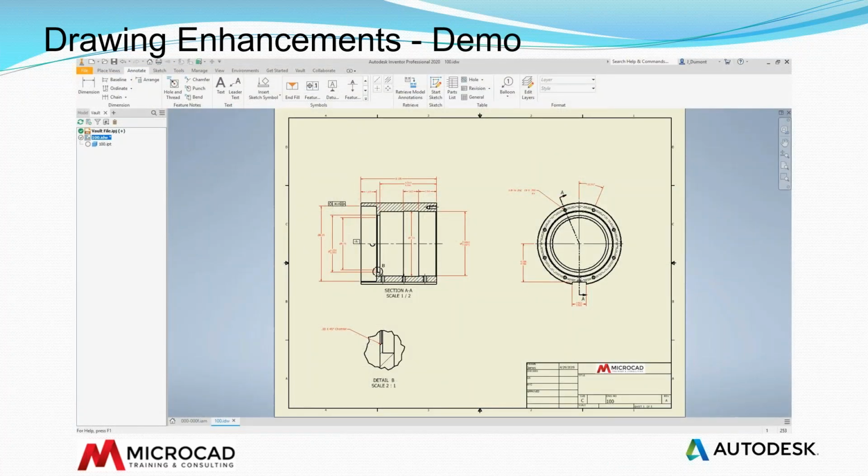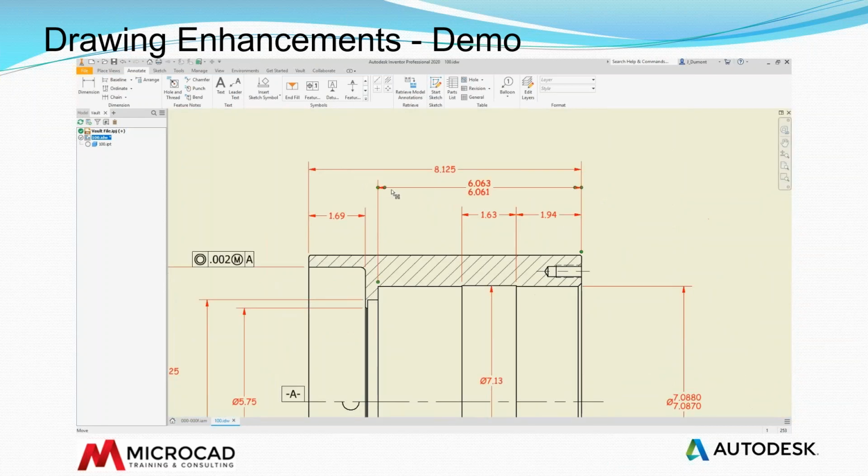So let's watch this brief demonstration highlighting the drawing updates. This video will show how to use the presets within the feature control frame. Now, presets are not new. They were introduced in the hole command in 2019. You had the ability to save a pre-configured hole configuration. Let's say that you wanted a blind tapped hole or a through counterbore hole, certain size or certain depth of the counterbore. We now have the presets within the feature control frame. Take a look at this a little bit closer.